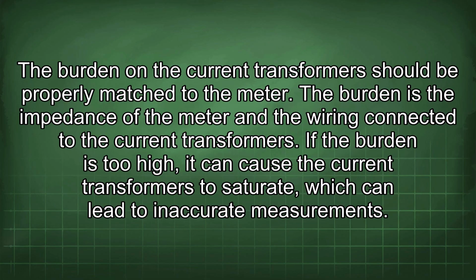The burden on the current transformers should be properly matched to the meter. The burden is the impedance of the meter and the wiring connected to the current transformers. If the burden is too high, it can cause the current transformers to saturate, which can lead to inaccurate measurements.